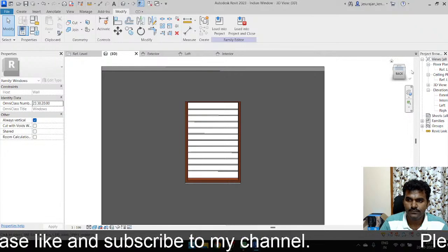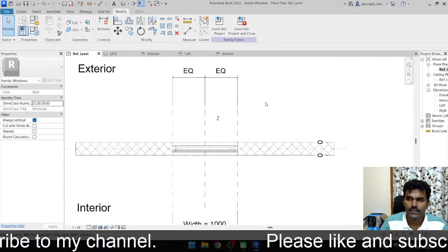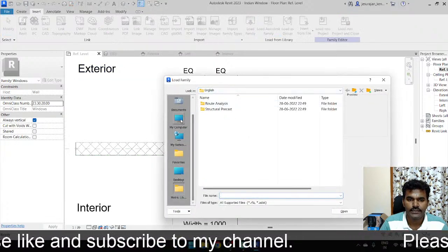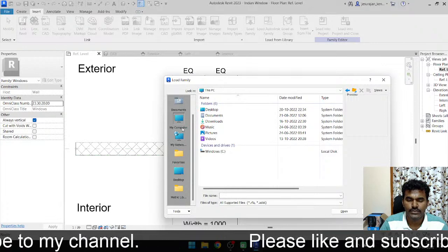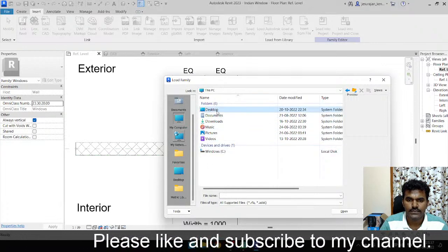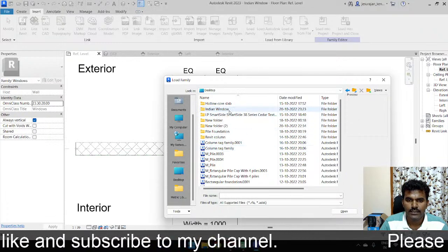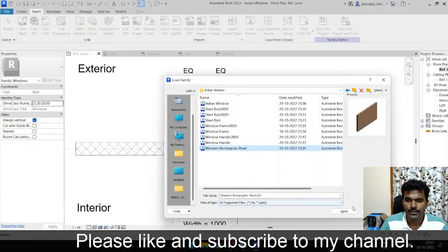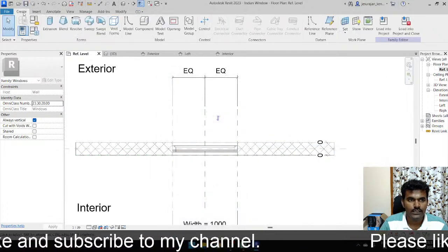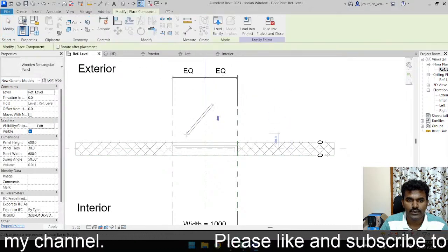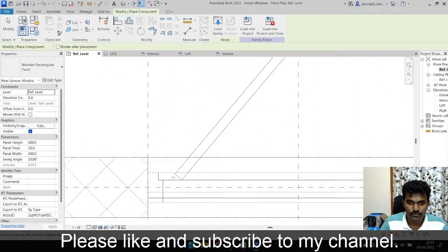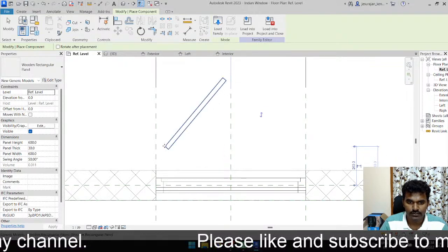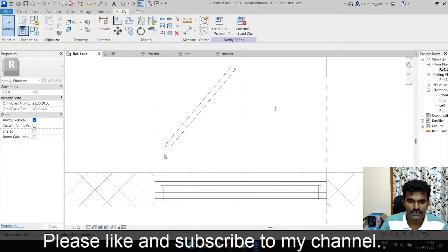Okay, so now let's go to reference level, go to insert, load family, and now go to my computer and desktop. What's the name? Indian window. Here, wooden rectangular panel, just open. Just place wooden rectangular panel here. You see here, the place where I'm holding is the origin point of the nested family. I have just placed it here.